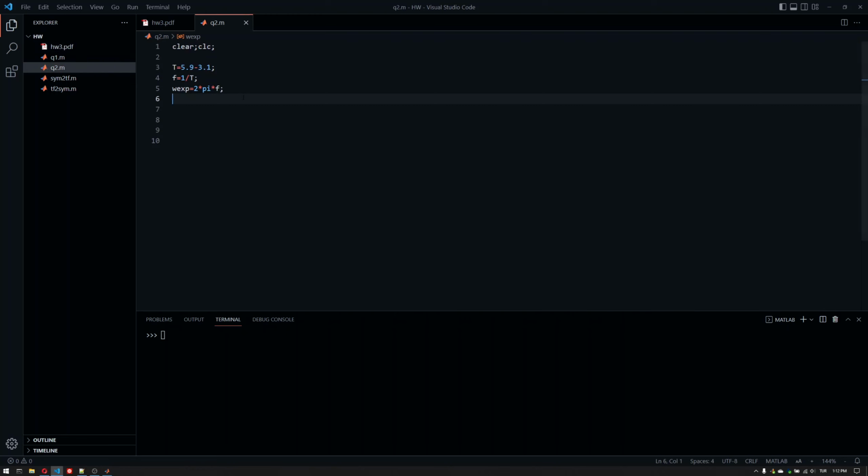And in these two cases, if we have a j omega crossing and if we have a j0 crossing for certain p-type controllers, and this is mostly for -k, what we will end up in is that a set of roots for the j omega crossing would look like this: s plus j omega and s minus j omega for that specific k value, which translates into s squared plus omega squared.